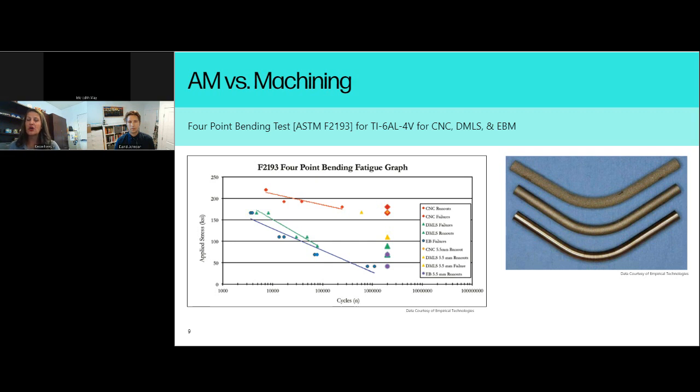But this is the cautionary tale of, okay, there are a lot of variables that go into something that is additively manufactured. You've got your powder, like we talked about, how many cycles of recycling, what's the ratio of recycling, how are the parts laid out for print on the plate, what are the specific machine specs. And one of the other conversations, in addition to the lot release testing, is dual source suppliers, right? So if, for instance, we used one type of machine and we had the entire process, and that's the thing that people forget, is that when you go for FDA clearance or approval, it's not the end product. You're freezing the entire process from the powder type, the concentration, the ratios, to the print bed, and all those things that we talked about, to the end result through sterilization and cleaning.